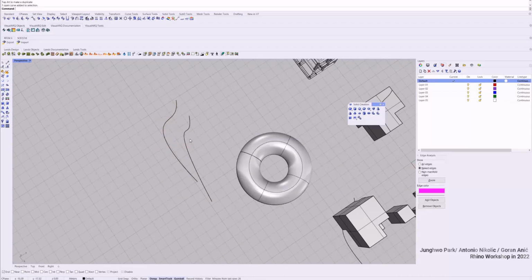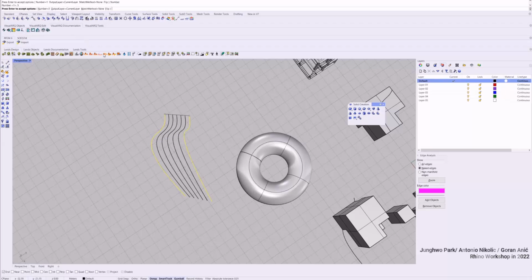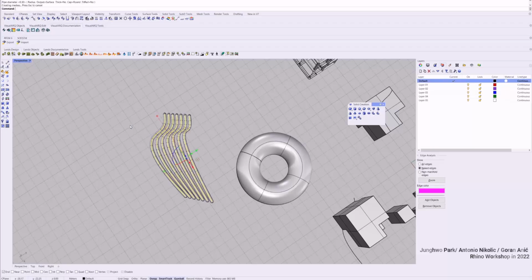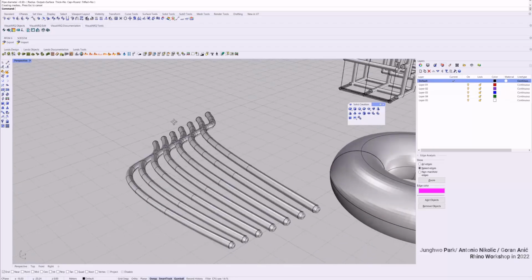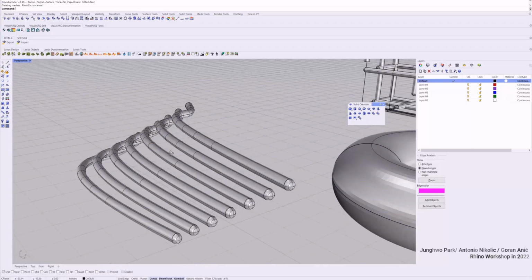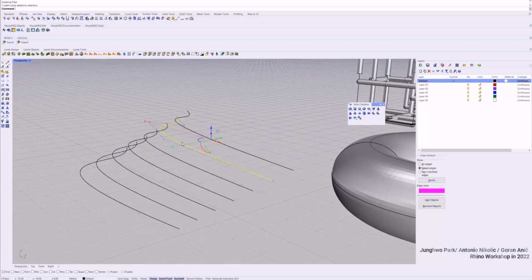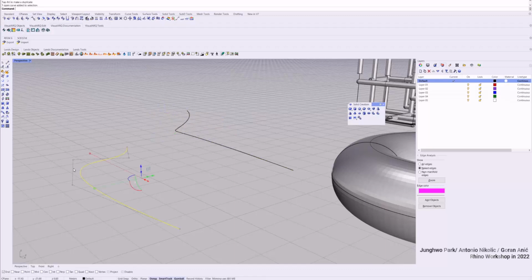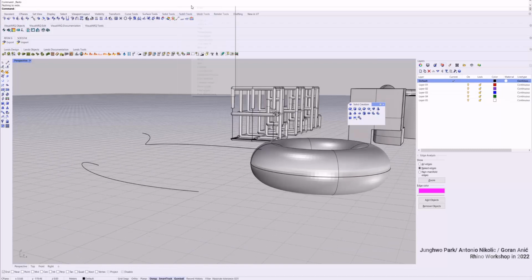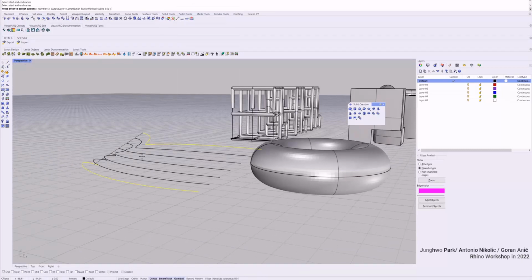In between these twin curves, we have a start and end curve, and I'll give the number maybe 5, and let's say this is a special conduit. This is an easy conduit, but what I wanted to show you was something like this that is difficult to model with Revit. You can twin curve this one and this one.